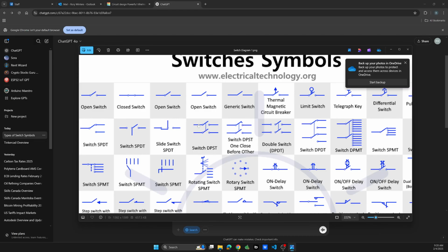So the pole can be connected to the throw in 2 positions, but the second pole can't actually touch the second throw. That's why it's only a single throw. Whereas in a double pole, double throw, you have the poles in the middle, and you could have the position to the right or the position to the left. So that's what makes it a double pole, double throw.